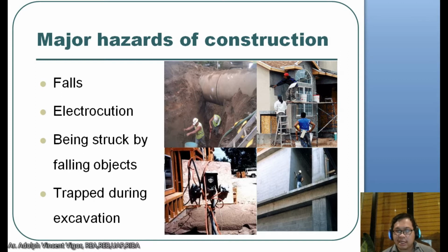If you don't take safety measures, if you're going to make a deep excavation and you don't have the proper support for the sides, it might collapse. Like this one, if you dig too deep and this area is not properly reinforced or shored, then there's a tendency for the soil to fill in. Okay, so it's really dangerous.